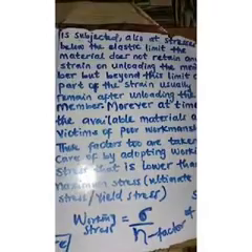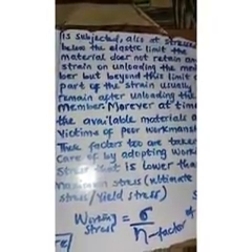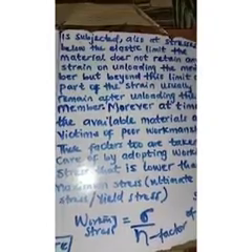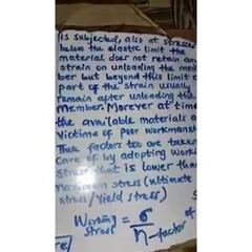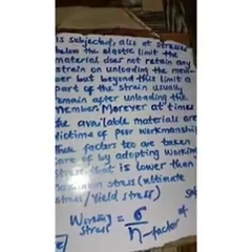It is impossible to accurately foresee the external loads to which a structure is subjected. Also, at stresses below the elastic limit, the material does not retain any strain on unloading the member, but beyond this limit, a part of the strain usually remains after unloading the member.